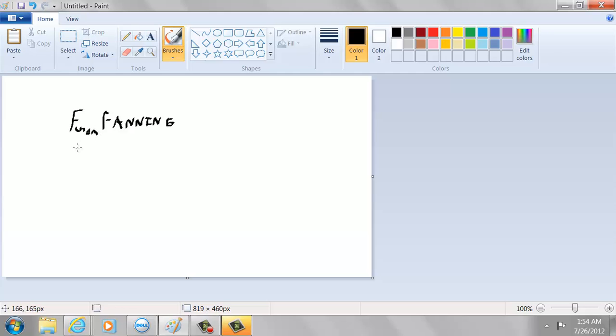This is not to be confused with the Darcy friction factor. And the difference between the Darcy and the Fanning is that the Darcy is 4 times as great. There is no 4 at the bottom of the equation as there is with the Fanning factor.